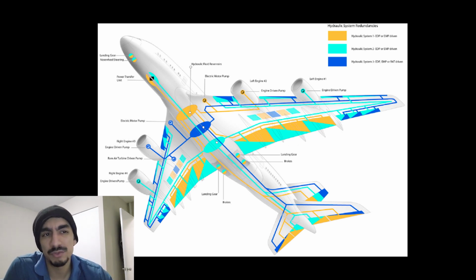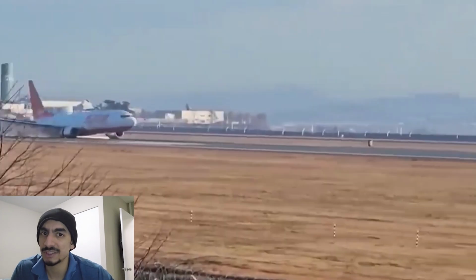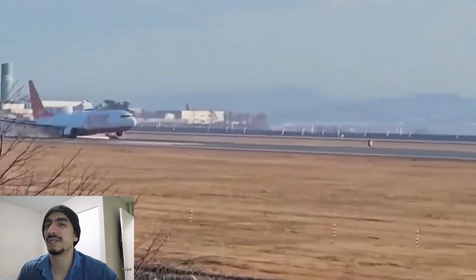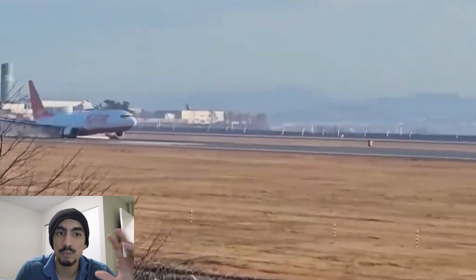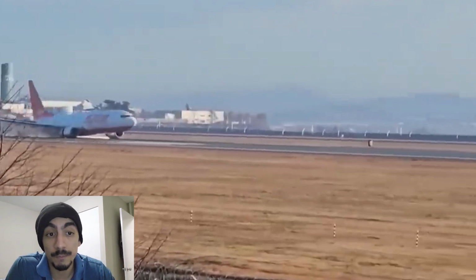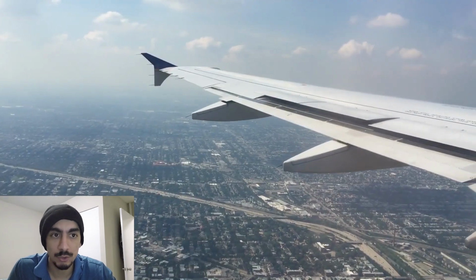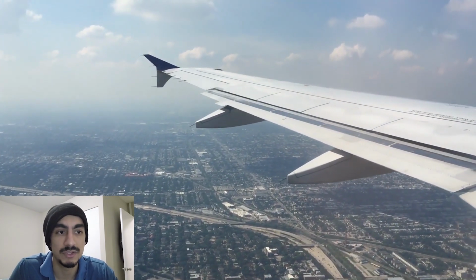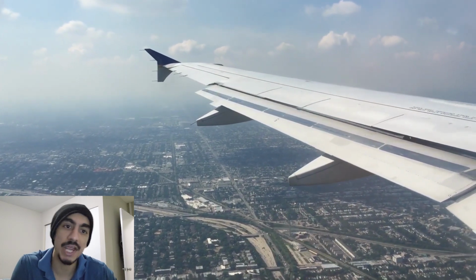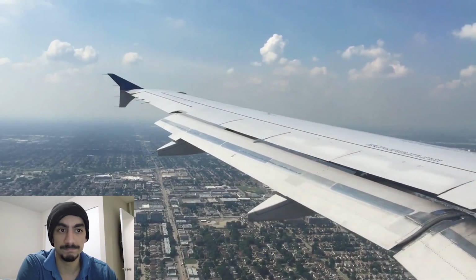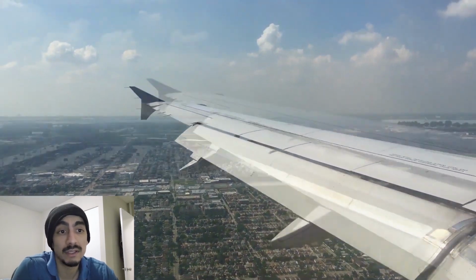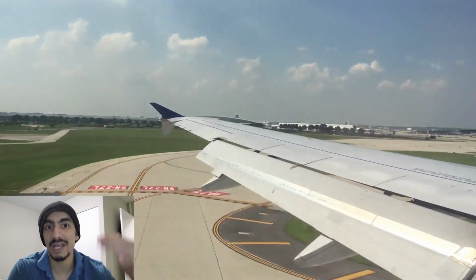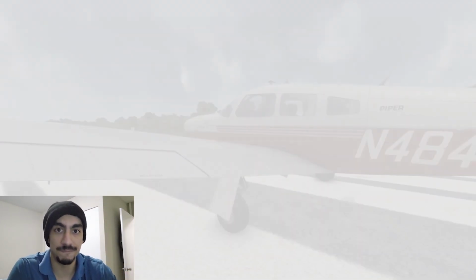So now let's dive a little deeper into the landing gear and the flaps, because, as we know from the crash, the landing gear wasn't deployed, the flaps were very minimally controlled, and let's see what happened. So let's analyze how it's supposed to work in a normal landing compared to what happened in the Jeju Air incident. Okay, so coming to flaps. Flaps are basically those moving surfaces on the trailing edges of the wings, as you can see here. In simple terms, they change the wing's shape and size, so that you get more lift at slower speeds. Because normally when you're coming in to land, you want to slow down without losing too much lift. Otherwise, you drop like a rock. So flaps help with that.